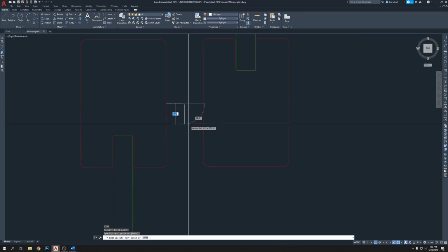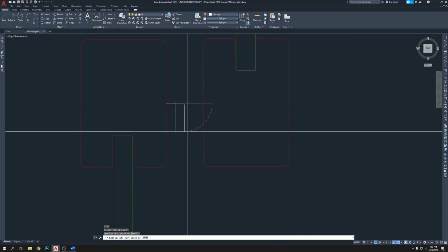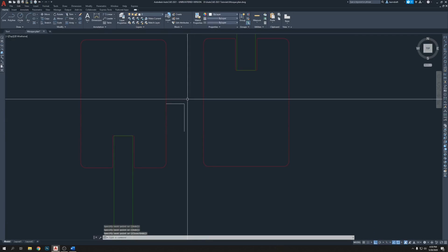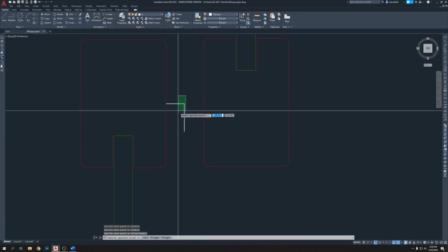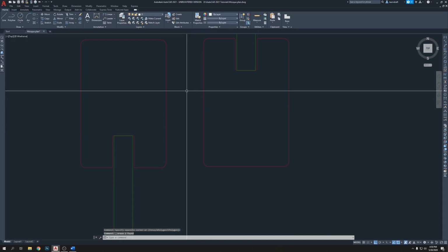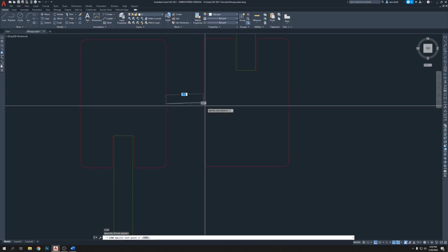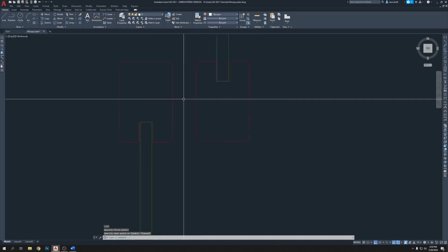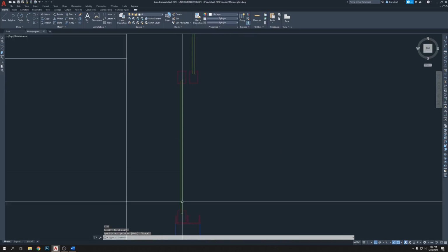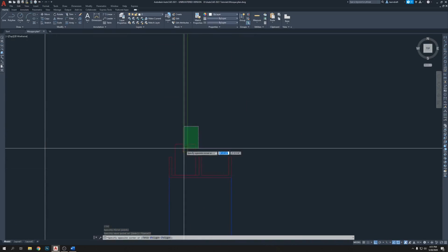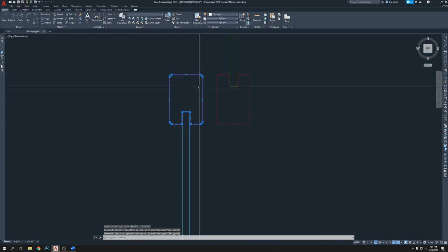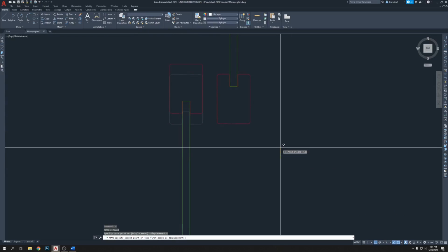I'm going to draw from the center, then I will move it. Click here, then click here, and actually we need to draw a polyline. It's better. So let's draw for single line. Okay, it's not actually straight because of this one in the end. So I'm going to push it for move 0.03125, which is 1/16 of inch.